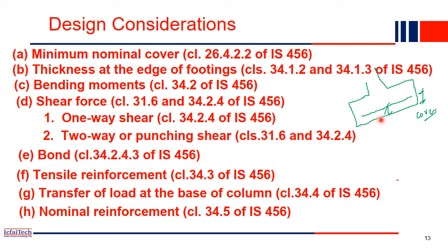So as per IS 456 clause number 26.4.2.2, the minimum cover is actually 50 for the footing. Minimum 50 we have to provide, because we can avoid many harmful chemical effects on the reinforcement. This is our first thing, that is nominal cover.